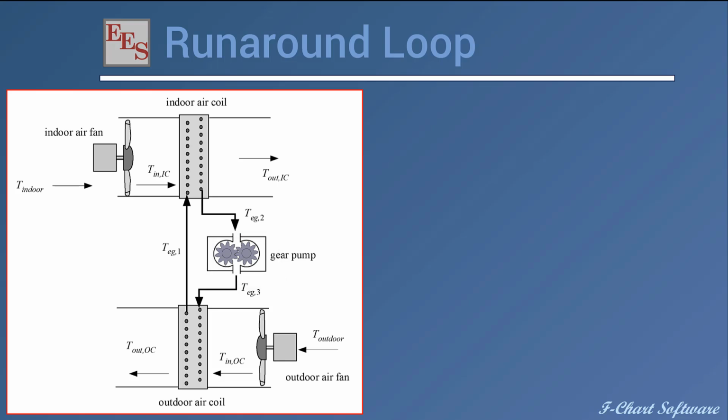So this is a system, and anytime that you're simulating a system like this with some complexity, it's probably good to start out with some upfront thought about what your strategy is, and in particular what are the inputs to the system, and then what are the things that you're going to want to change, and then most importantly, what are the variables in the system that have to internally be iterated on in order to make the system converge. So I've tried to do that here.